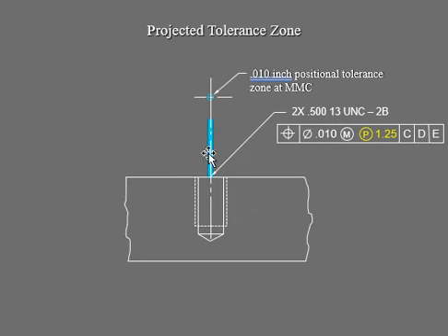All right, now we'll get into the zone. That zone, we have an MMC right there, don't forget it. We're going to point that down, and that's your axis. That's our plane that we study with our coordinates, so you can see the center of that axis. And of course, this is your depth and the hole right in there. You have two of them, with this thread note, and the thread note is going to tell you everything about it: the depth, your thread numbers, internal, external, everything in it.